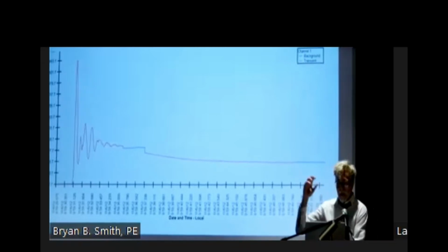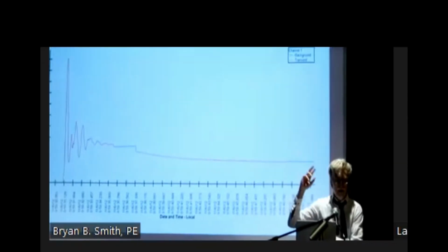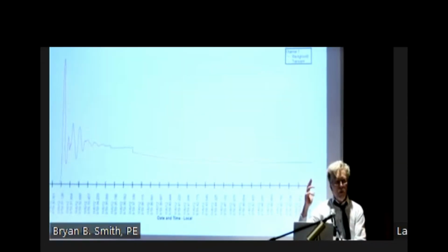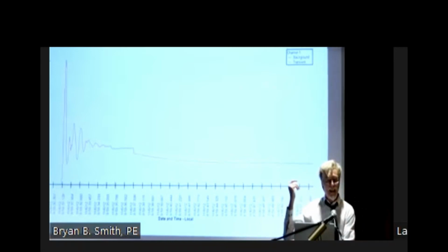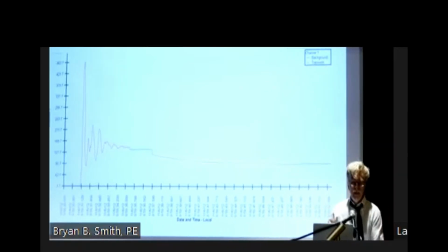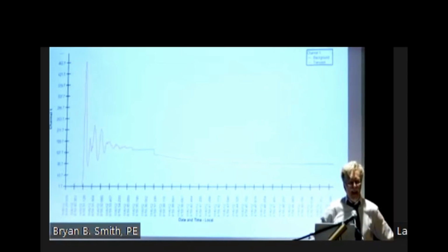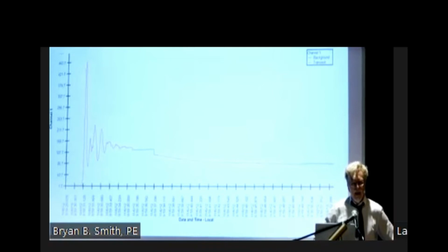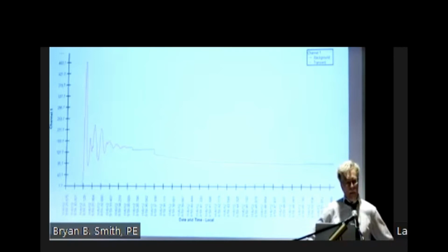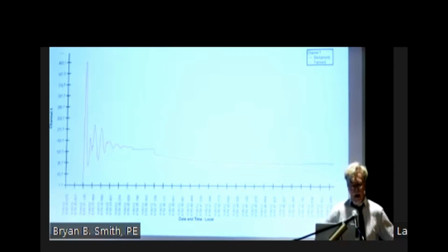And again, my pet peeve, vertical turbine pump. If this is a water well, okay, I have an air vacuum valve. I have a static water level down like 40 feet. I turn on my pump, and now I'm going to move the air out of an air vacuum valve. And what's my pump and motor doing? Well, this is an easy job. I have no back pressure.